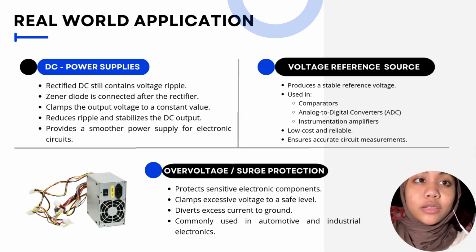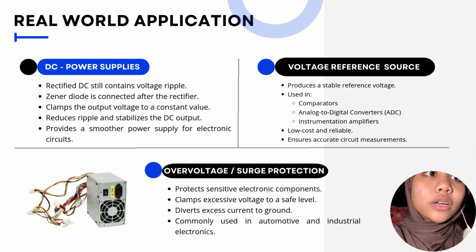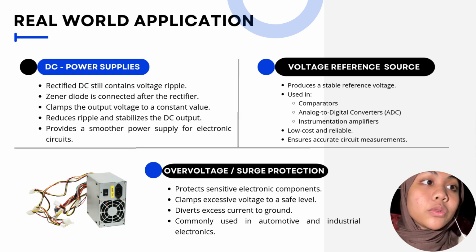The third one is over-voltage and surge protection. It protects sensitive electronic components, clamps excessive voltage to a safe level, and diverts excess current to ground. It is commonly used in automotive and industrial electronics.